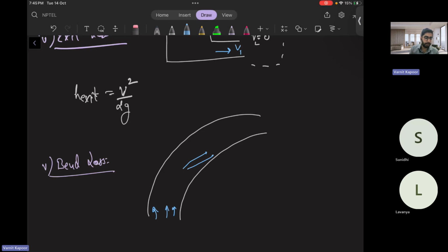Because of the pipe bend and the spacing between the streamlines, a high pressure zone is developed. The spacing between the streamlines will increase towards the outside wall and decrease towards the inside of the bend. Because of that, there will be a pressure jump. P will increase here, a high pressure zone, because most of the fluid started accumulating here because of the presence of the bend.